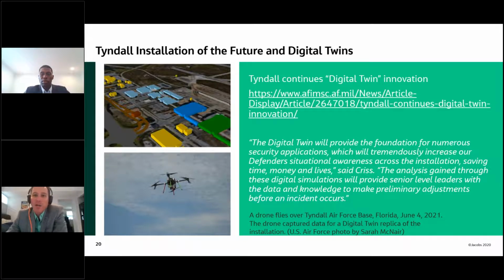Part of what we did is we created a 4-dimensional model, so 3D plus time, one small component of what we could consider a digital twin, because it was, for us, a decision-making tool. It helped us understand construction sequence, potential installation, time-space conflicts with, again, an entire base being rebuilt, all new utility infrastructure, some existing infrastructure, but mainly all new coming in, and starting to tag that information through our modeling process. Now, like I said, you could call that a digital twin from a 4-dimensional perspective.